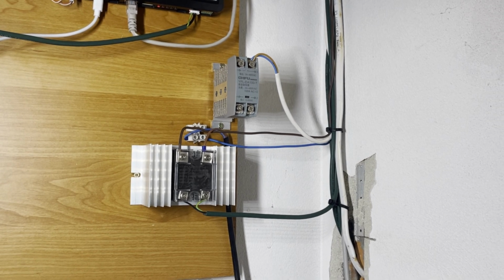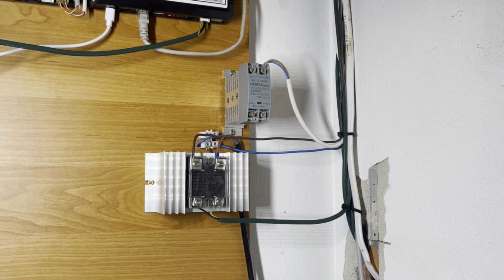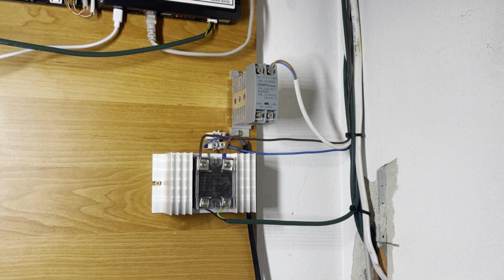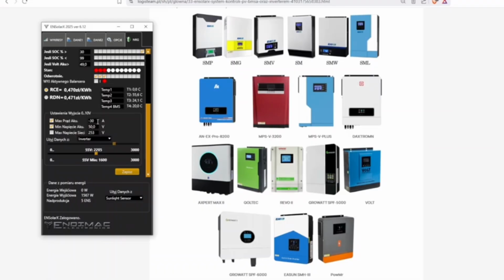And now look, because in this latest version something like this came out that we can control this heater in the energy tab. We have such options in which we set what the power limitation on this heater should look like. So I have set that the maximum current from the battery should not exceed 30 amps. There was no such thing before, because if the consumption appeared below 0, i.e. it already saw minus 4 amps or something like that, it would immediately drop the output from 10 volts to minimum. How do we know it's to minimum?